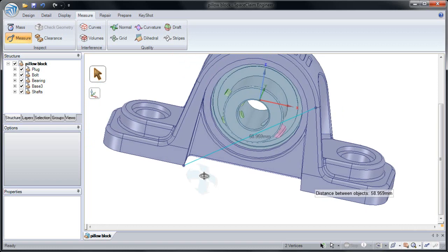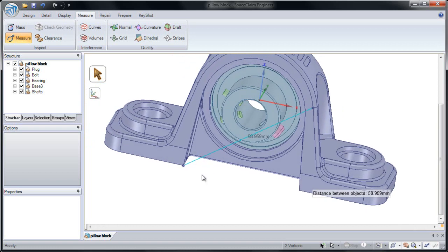Now if I want to get the X, Y, Z distance, I can use our tool guide to let me select a plane or an origin. By clicking that tool guide, I can measure along an edge. So it gives us our straight distance and then shortest line.